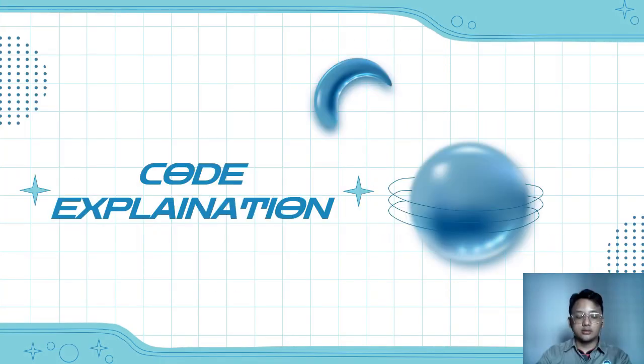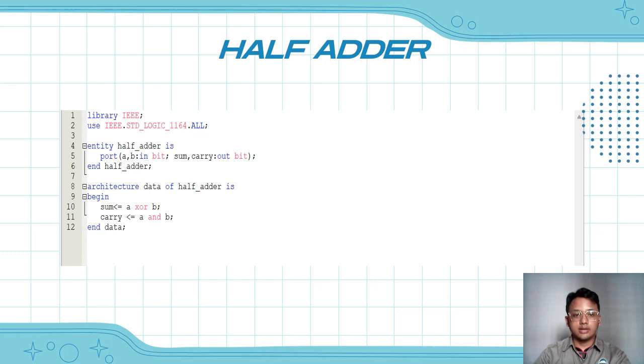Next, we proceed with the code explanation. So the coding starts with the half adder. The library IEEE and the use IEEE.std_logic_1164.all will be declared, and of course the design entity will be declared too. For the entity, the ports A and B will be assigned as the input, and the sum and carry will be assigned as the output. And for the architecture, the sum will get the value A XOR B, and the carry will get the value A AND B.